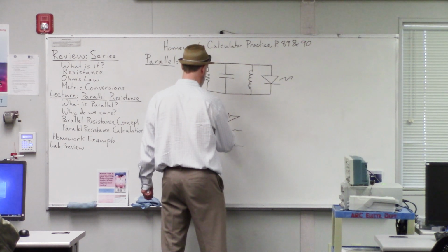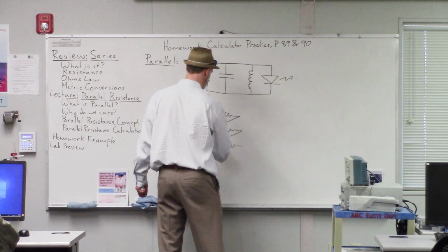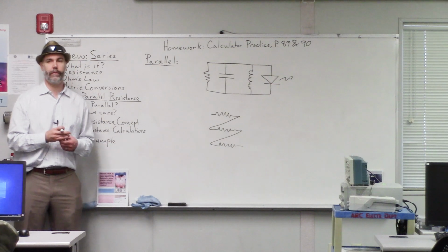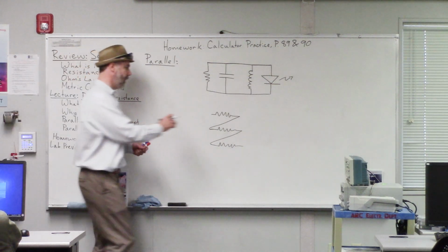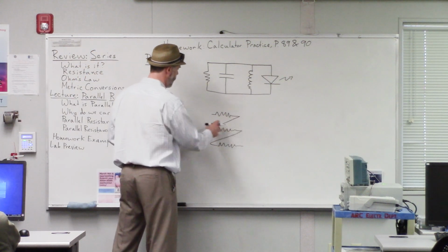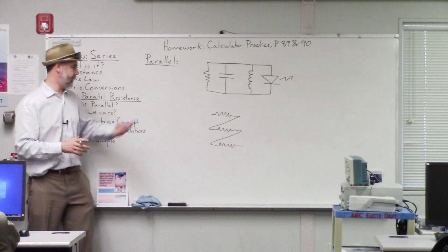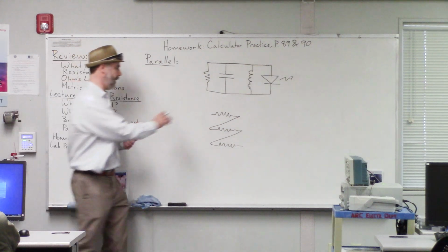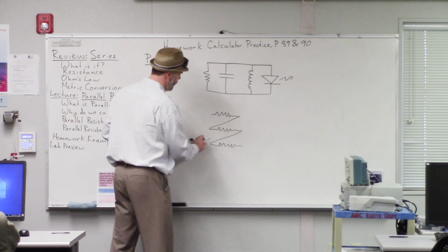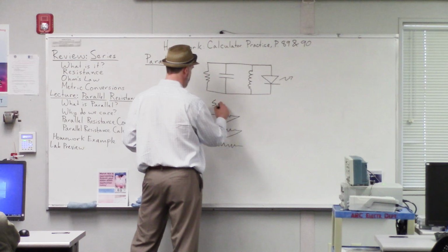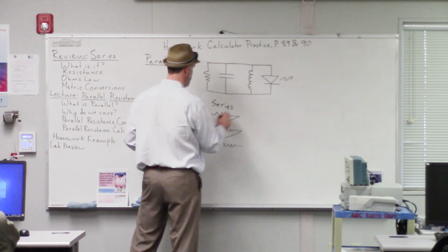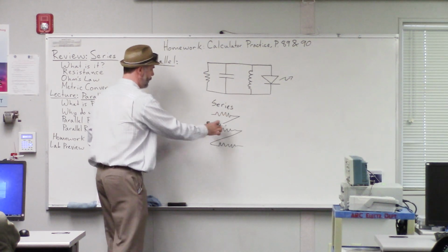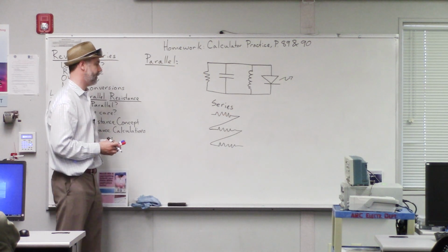And we'll connect them together like that. Are those in parallel? No, exactly, because what are they? Is there another way of saying what they are? They're series, exactly, because the end of one is connected to the beginning of the next. So these are in series, not parallel. Even though they're kind of side by side, the connections show that they're actually in series, okay?